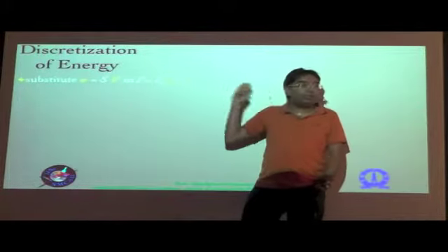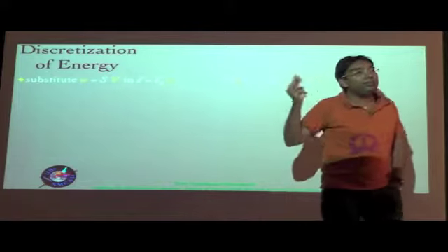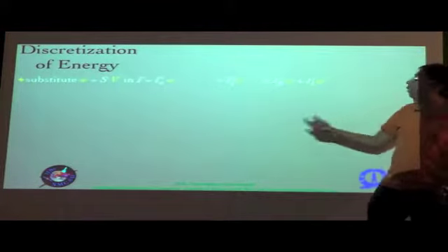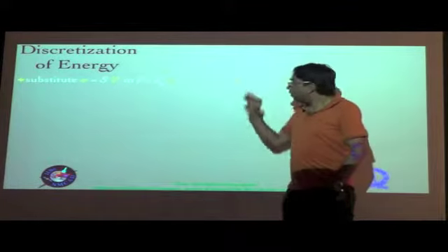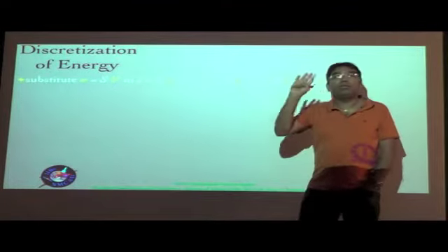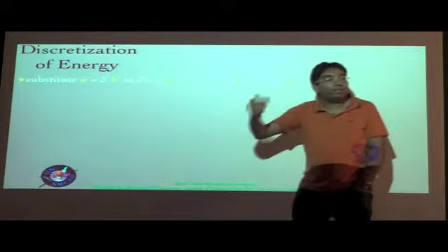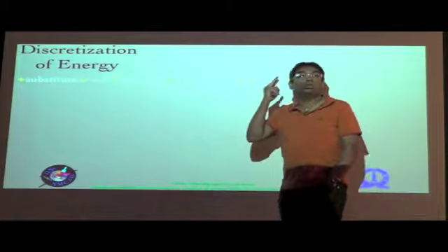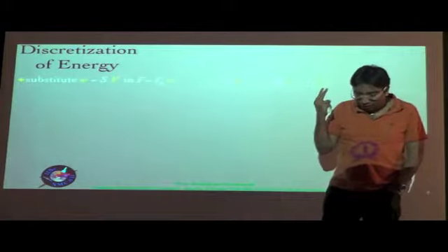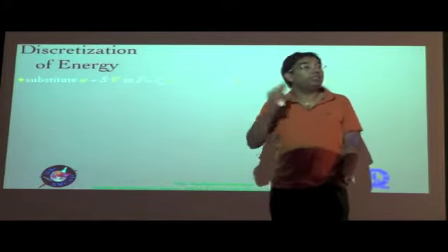And remember that the 3D strain was broken up into 4 parts, 3 depending on the warping, 1 depending only on the strains epsilon bar. Still we deal with only the 4 degrees of freedom, which the variational asymptotic method itself basically brought about. We are not bringing in those 2 additional degrees of freedom, which is basically the transverse shear strain measures.